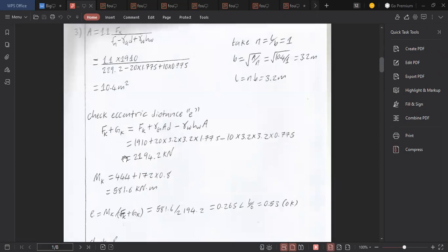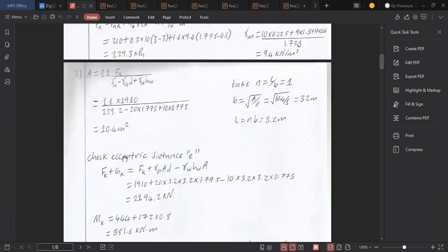After you answer question 2, we go to question 3, where you want to find the size. So the dimensions, you want to find the length and the breadth of your foundation. To make calculations easier to follow, as Faith did and I also followed, make your foundation a square, same length and same breadth. I think that's much easier to deal with than calculating for a rectangle where they might be different.